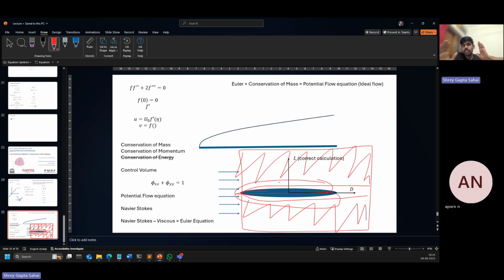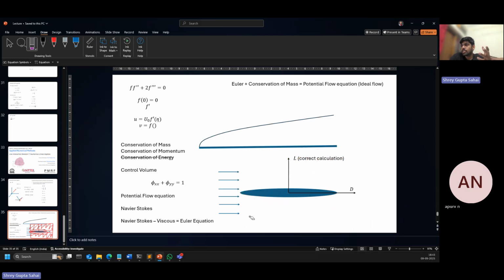You get the idea, right? That the majority of the flow is not viscous. So how come viscosity has such an important effect, especially on drag? Why is the drag not zero? And this is where Prandtl's boundary layer theory came in.